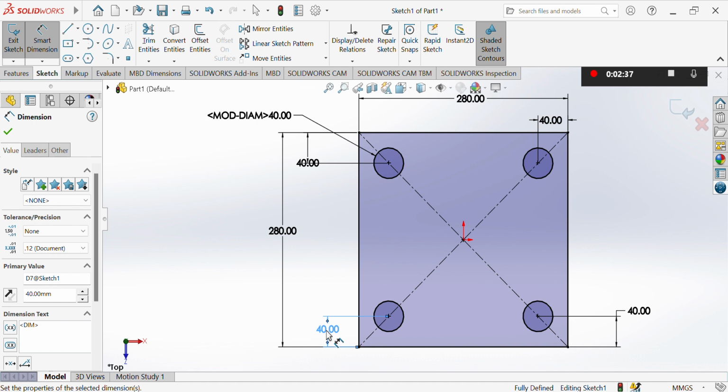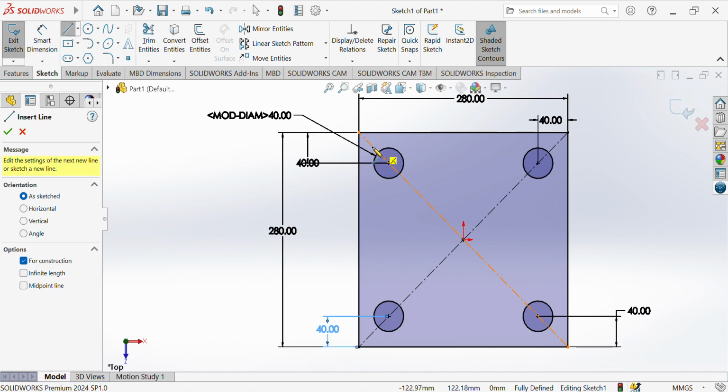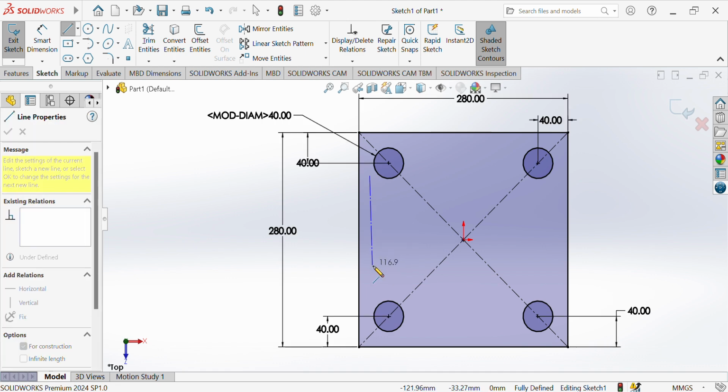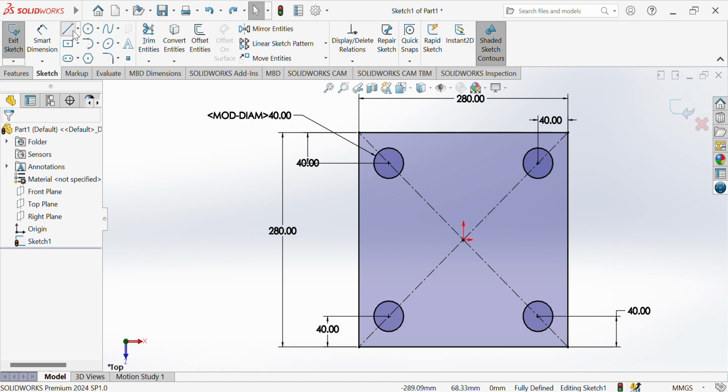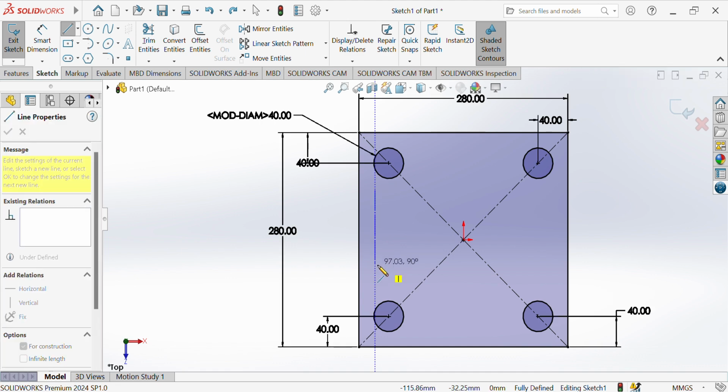Okay, then the next thing we have is circles that are coming at the side here. So let's use a center line so we can get that midpoint. So we have a line somewhere here. Let me do that again. Selecting your center line, just draw a random line.